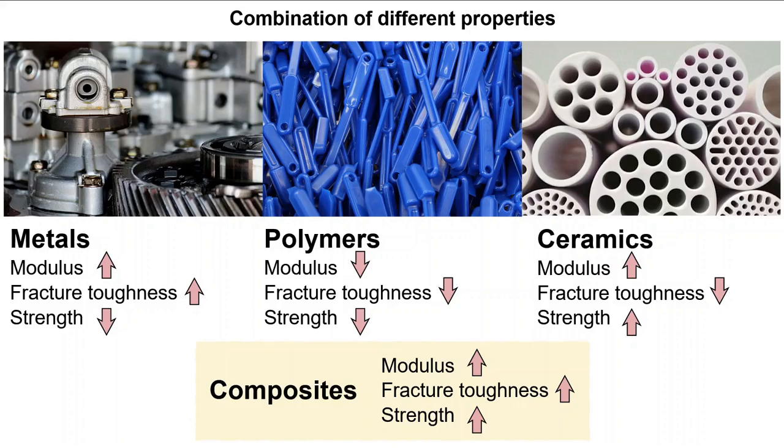The contribution of carbon fiber to the polymer increases strength and modulus. Silicon carbide particulate reinforced aluminium, or Al-SiC, is more apparent, acquiring the additional strength and moduli from the ceramic, whilst retaining the fracture toughness imparted by aluminium.